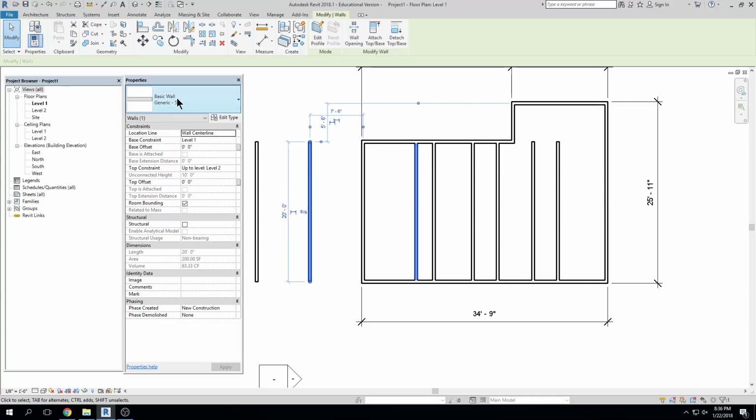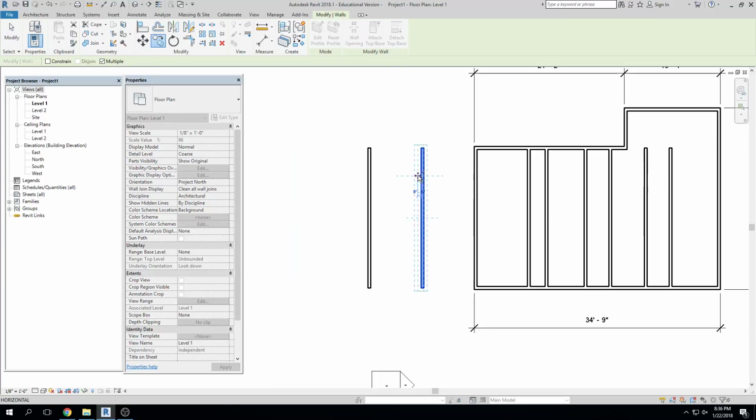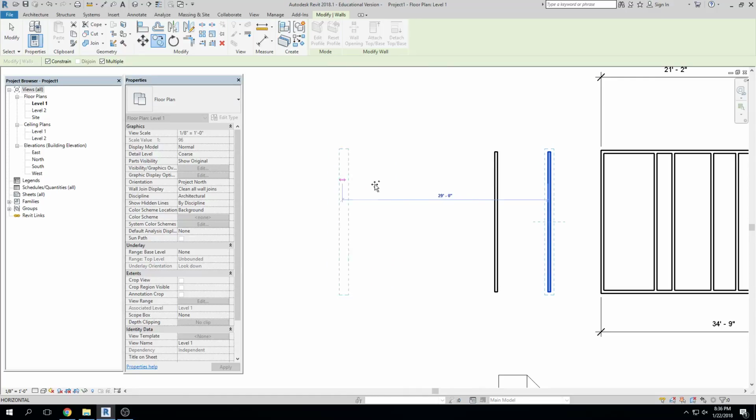You found it. Okay, select the object, click on copy, click, and if I want multiple, then I click on multiple. If I don't, I uncheck it. Okay, constrain. Click on constrain. It will only allow me to move, like ortho basically, back and forth, right? It doesn't allow you to go up and down. It just allows you to move in an exact straight line back and forth.